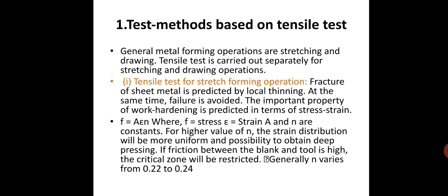Then the average value of the sheet metal radius is determined by orienting the axis of metal flow at 0 degree, at 45 degree and 90 degree.